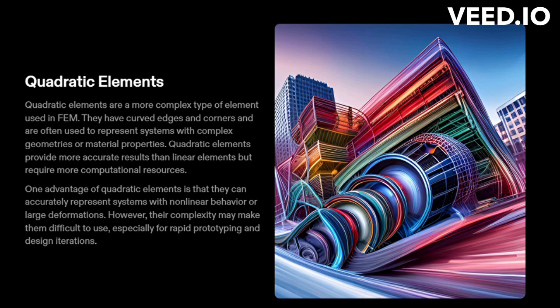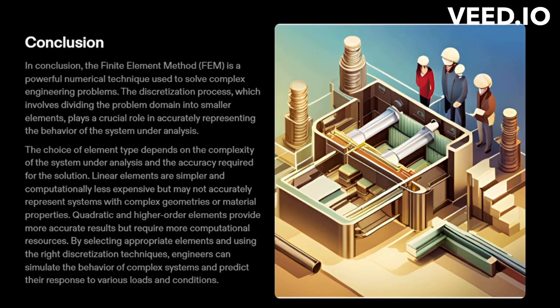Quadratic elements are a more complex type of element used in FEM. They have curved edges and corners and are often used to represent systems with complex geometries or material properties. Quadratic elements provide more accurate results than linear elements but require more computational resources. One advantage of quadratic elements is that they can accurately represent systems with non-linear behavior or large deformations. However, their complexity may make them difficult to use, especially for rapid prototyping and design iterations.